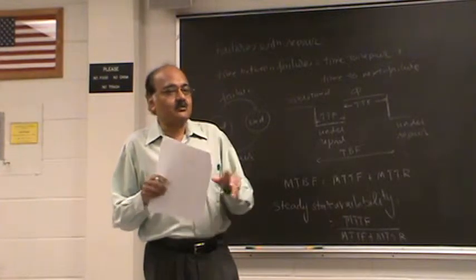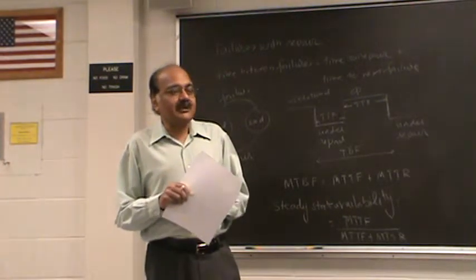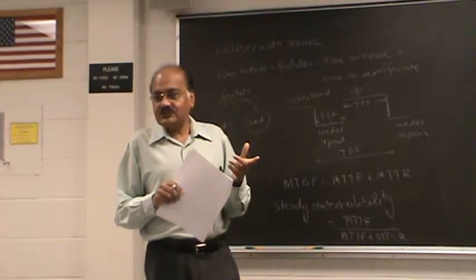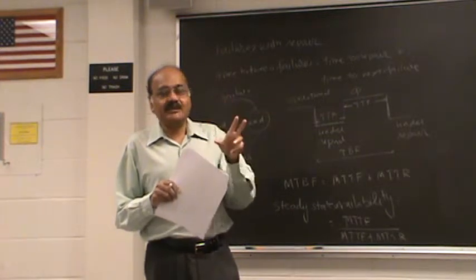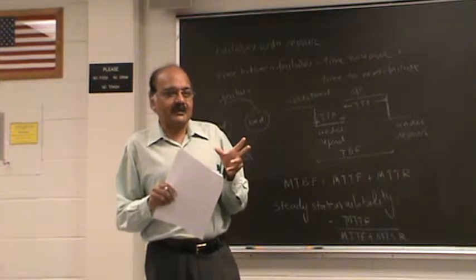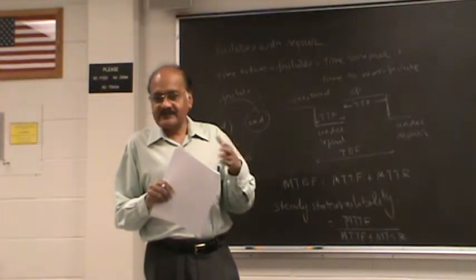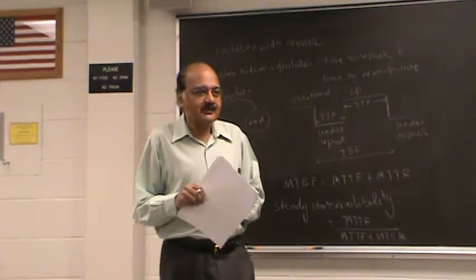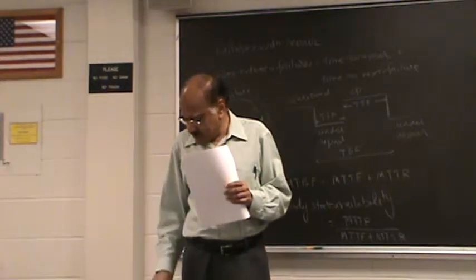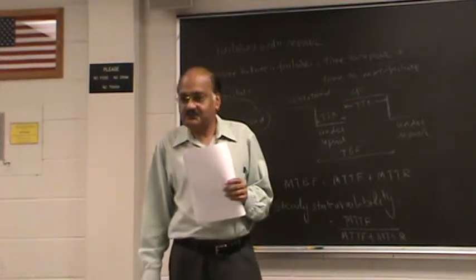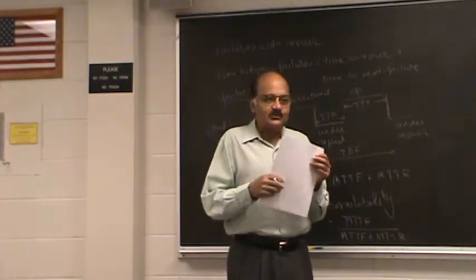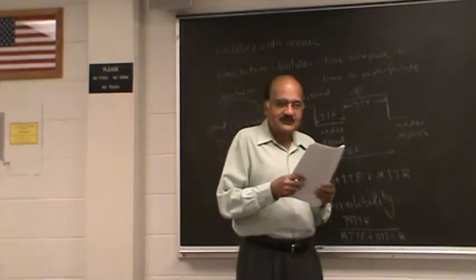Now, sometimes the question can be, come up with an implementation which is redundant. And in that case, you have to create a redundant term, which is still correct, so it will still work correctly, but it will introduce a redundancy. And as a result of the redundancy, there could be some untestable faults in it. But in this case, if the question is to come up with a non-redundant implementation, that is what you usually do with Karnaugh maps. Okay. So that's a usual thing. Okay.